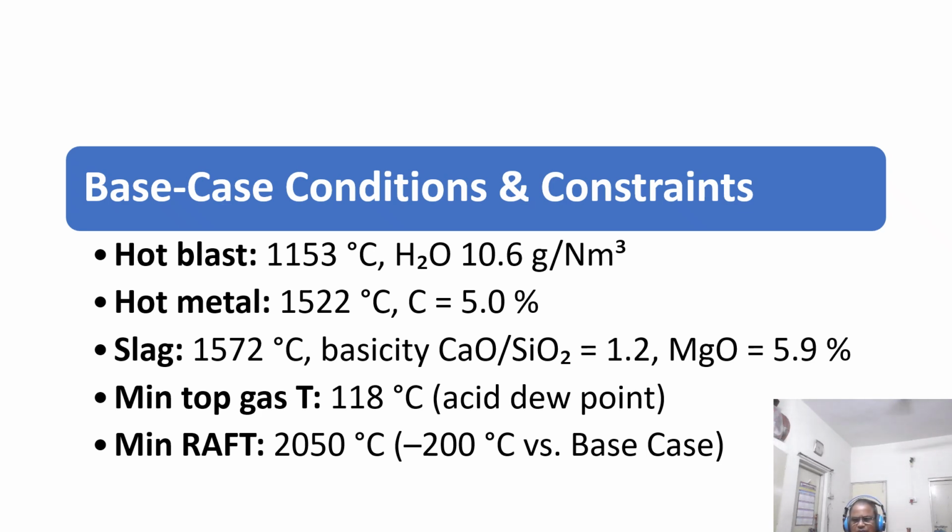Similarly, hot metal temperature 1522 degrees centigrade with 5% carbon. Slag temperature 1572 with a basicity of around 1.2.